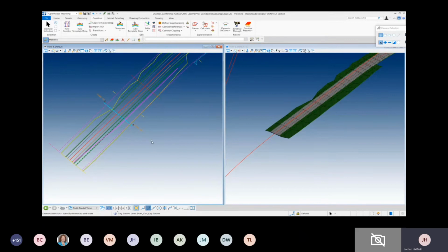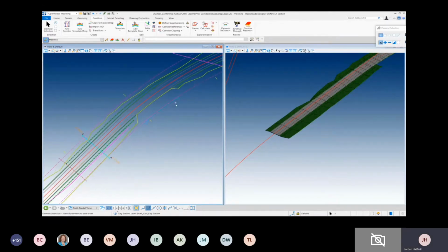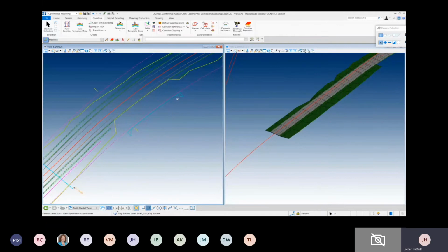In this case, we have key stations. I can simply slide them up and down graphically. I don't have to go to the corridor object, key in a new station, or go to the property provider. I could do a precision key in here, and maybe I want this at 90. Just key that in, and it moves accordingly. I could check them visually. Makes it handy.